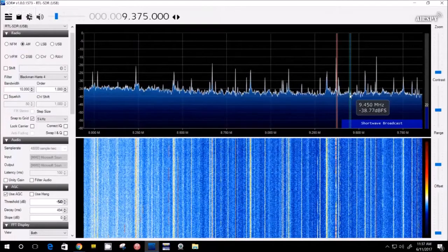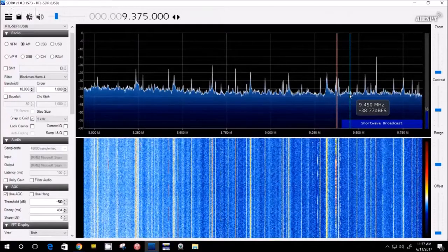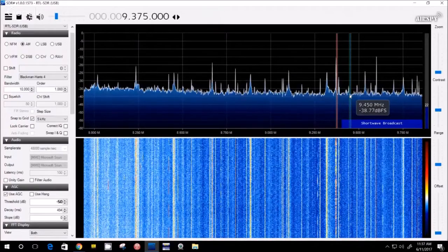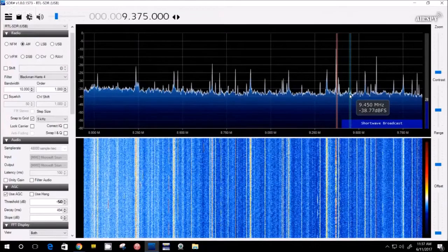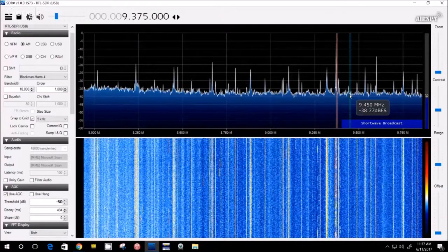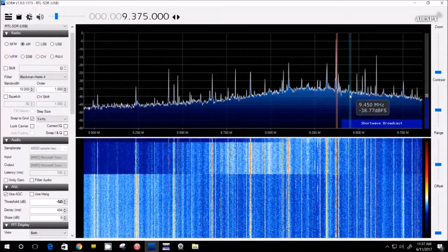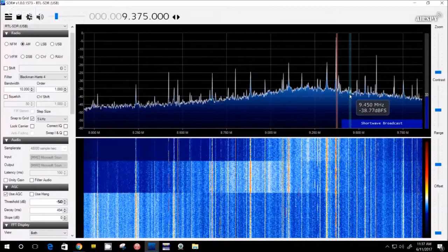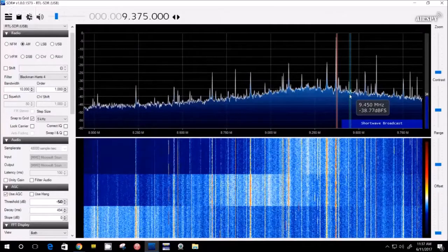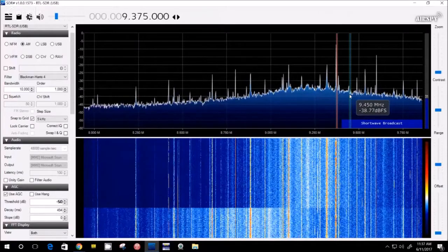That's the beauty of using an SDR. You can visually see the effects on the signals. So we're going to go around the knob here. Little effect. Little effect. So you can see the lower frequency there, 8 megahertz, is getting attenuated.